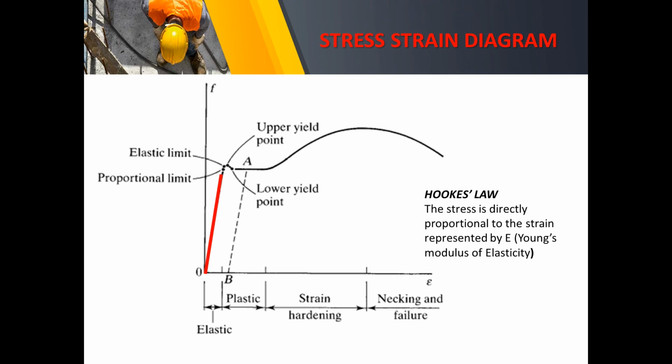It is represented by Young's modulus of elasticity. Within this limit, as you can see, as we increase your load, there is also an increase in your elongation or deformation, or the strain. In short, they are directly proportional. Hence, Hooke's law can be applied.